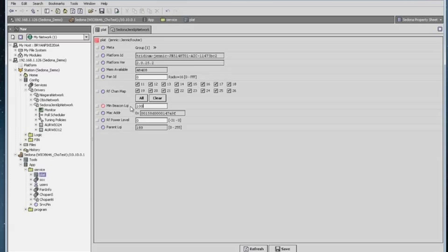So typically we'll make this 100 to 120 to give a higher threshold and more room for error on the lower side. So if it connects to a device, it has to have a starting link of 100, and then it can drop down to 70 without a disconnect. So very important feature here as you build networks to know that you can adjust that on a scale of 0 to 255. 70 being the absolute minimum we would ever want to see, but again, anything 100 or better is what we start with.